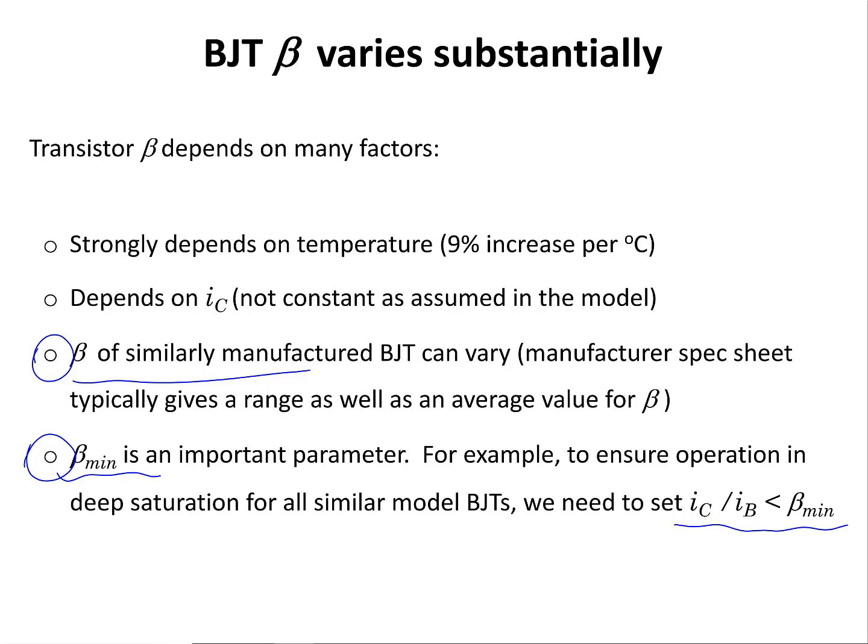In summary, today we looked at the BJT transfer function for one of the commonly used BJT circuit configurations, and we saw that the output of this BJT circuit is going to be at high value when VI is low, and for the cases of VI greater than VI high, the output is going to be at the low value of V saturation. Thank you for watching.